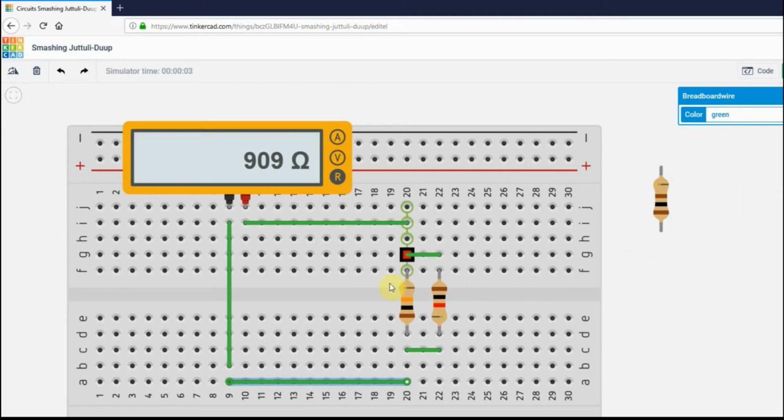This is something else for a further class. But whenever you have resistors that are in parallel, connected together like this, it is always less than the lowest value. The lowest value here is 1,000, and this is 900 ohms, or 0.9K.